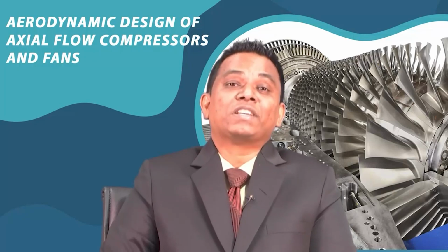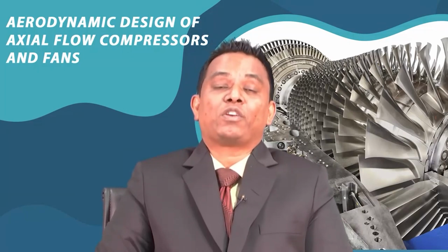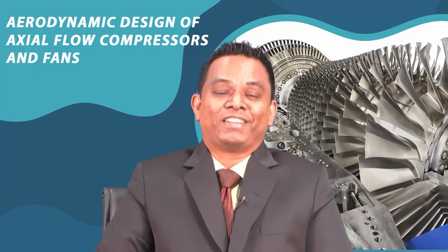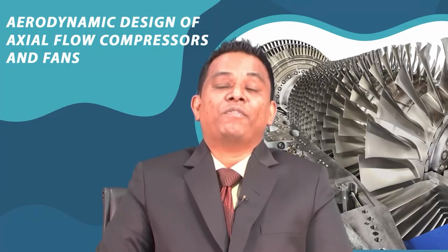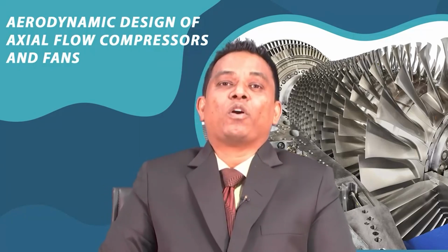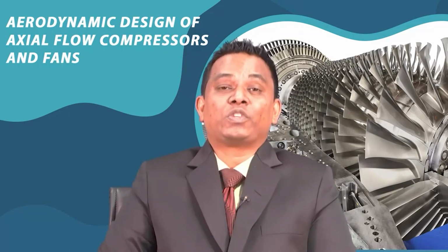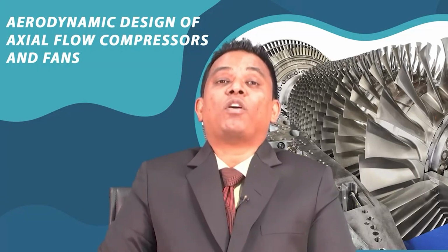We also have discussed how we decide the number of stages, because this is a very crucial part when we are talking about HP compressor. And we also have discussed how we decide with our parameter called flow coefficient, how we decide our axial velocity, and what is the meaning of having relative velocity to be different.